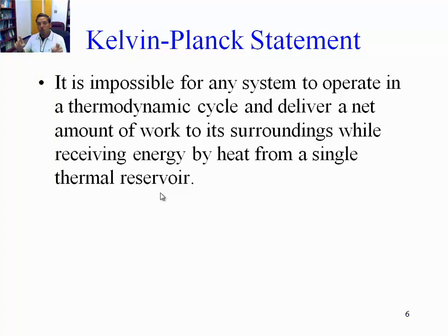And that's what happens in all power cycles. In order to create work, you need to absorb energy, but that's not enough. You also need to reject energy somewhere in order to produce a positive net amount of work. So you need at least 2 thermal reservoirs in order to do this. And it sounds very simple, but it's actually a major consequence. It has major consequences in the definition of efficiencies and the formulation of the second law of thermodynamics.